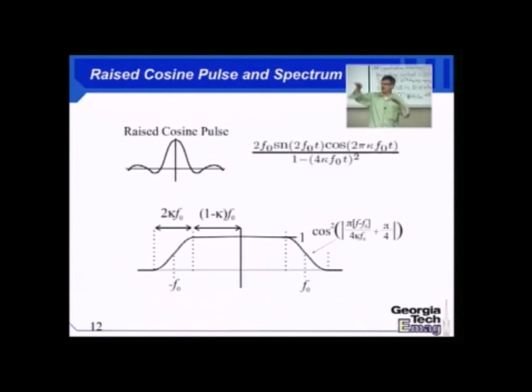The trade-off is that you have to include a little more margin of error to account for these cosine transitions. So your signal might take up a little bit more bandwidth immediately around the center frequency, but those little spectral lobes that you see ringing off will dampen more. And so this is a nice tool that the communications engineer uses to design their pulses.